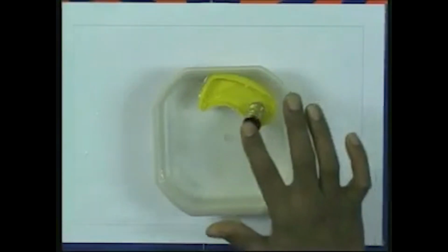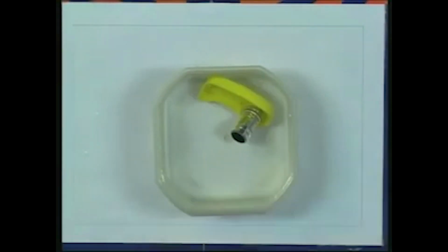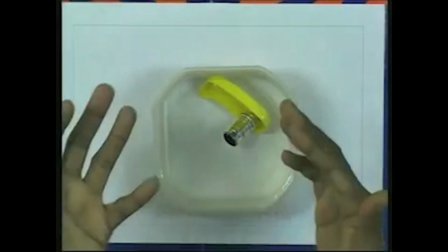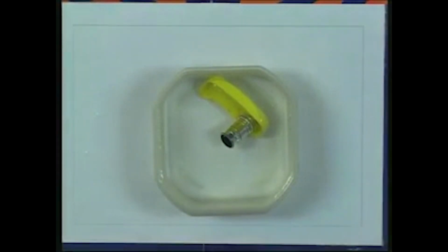But here it is overturning: an overturning couple is formed and then it goes down. So you can see the body is said to be in unstable equilibrium, since it has gone from the previous position to a new position, an overturning couple took place, and the body is not allowed to restore its original position. This is the so-called unstable equilibrium.